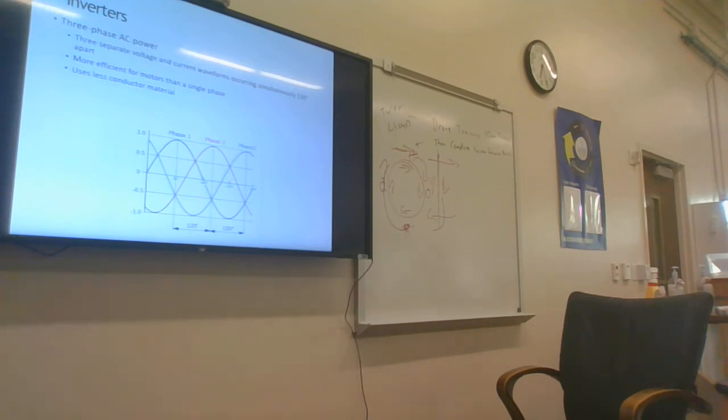So what's happening as the rotational generator moves around, the electrons that are forced out of this coil go through a load and come into this coil. And then by the time they're pushed over here, they're pushed out of this, through load into the other. So I have a different voltage between each of these coils.